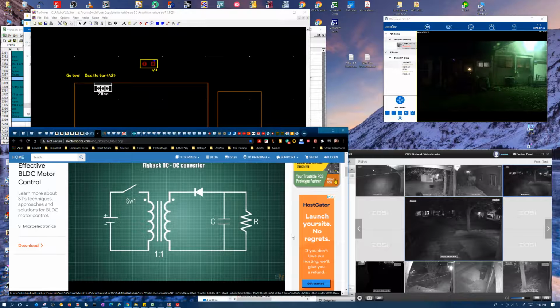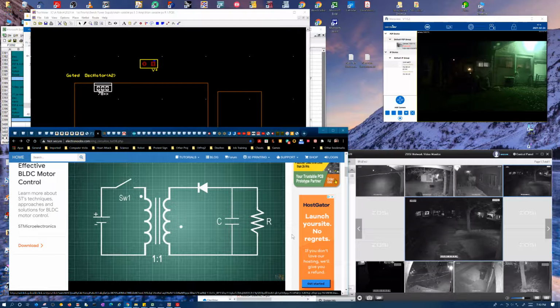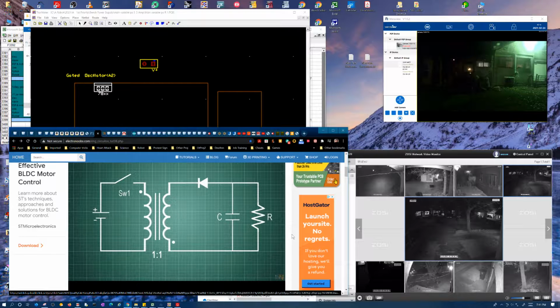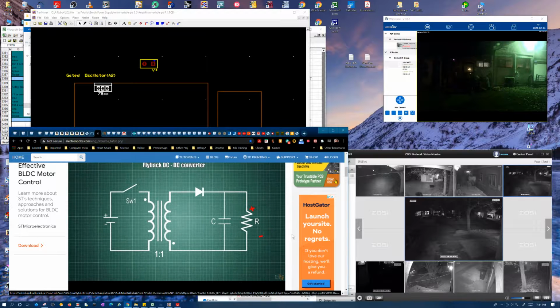And to get a positive voltage, what we have to do is to invert the secondary coil, so now the dot will be placed at the bottom here, and also to invert the diode. So now we have a voltage at the output of this polarity. And if we also add a capacitor, we could smooth the output and store the voltage. And basically that's how the flyback converter works.